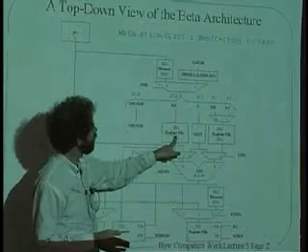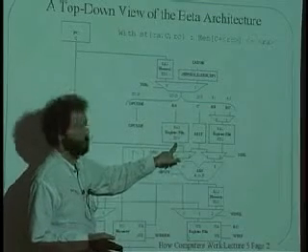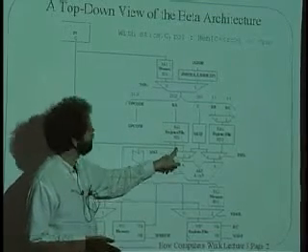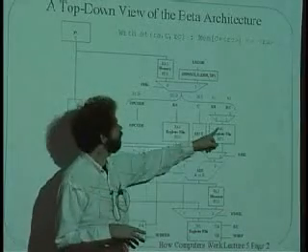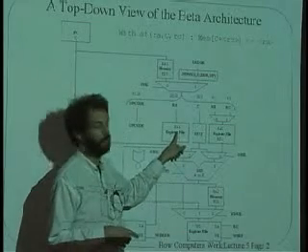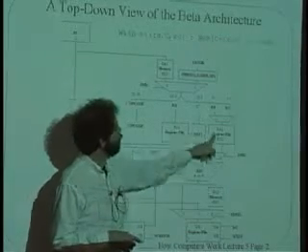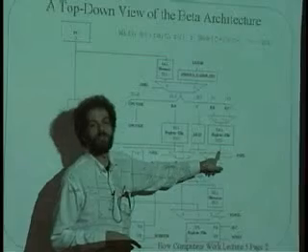And the results of whichever register it picked were supposed to come out here on RD1. And similarly, this was another port into the same register file that selected one of the same 32 registers, and whichever one it chose was supposed to come out here on RD2.